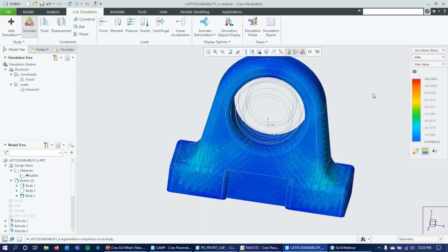The goal is just to reduce material in the most effective ways. So the way this is done is it's incorporating that data so that we can make a lattice that uses a very low amount of material, but that still divides the stress very evenly. And if we didn't incorporate these simulation results, we would not be able to obtain these max stresses with this little material. That's really what it comes down to.